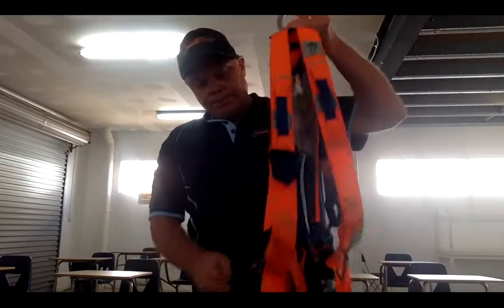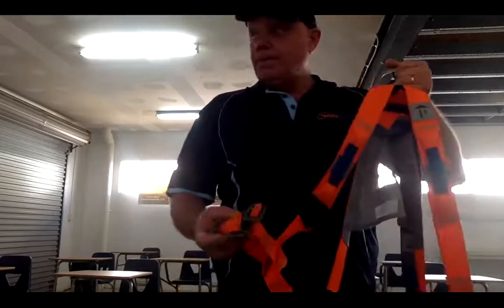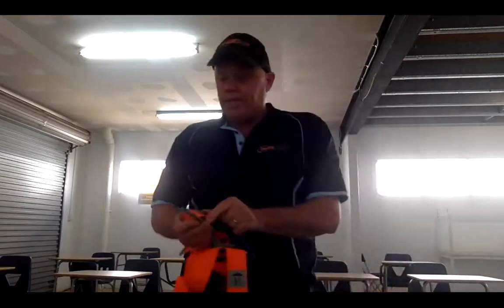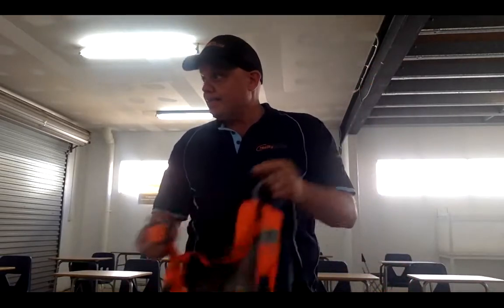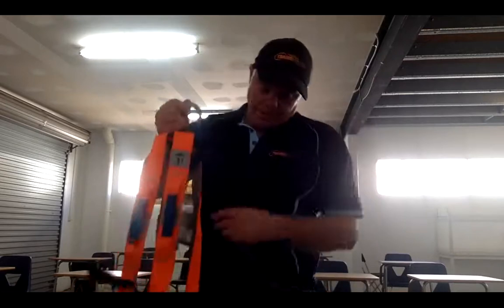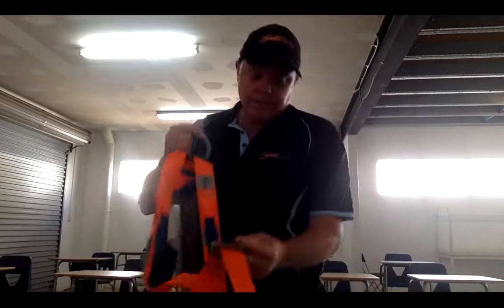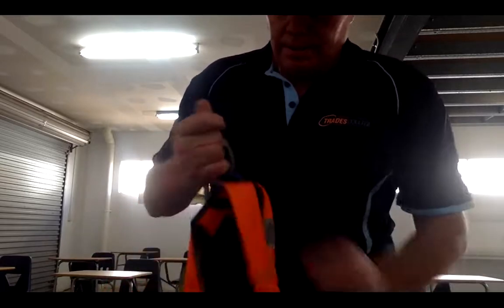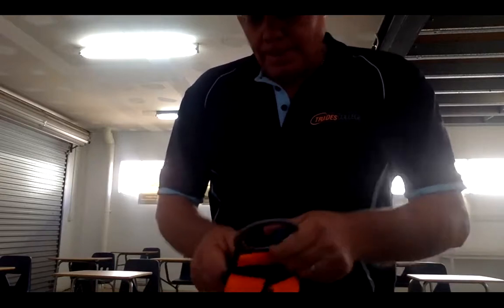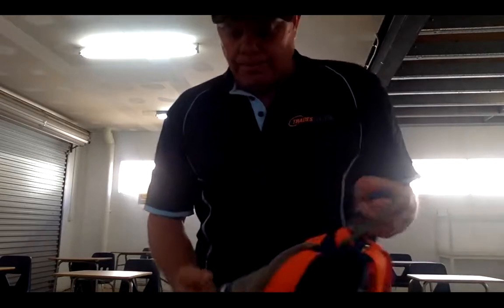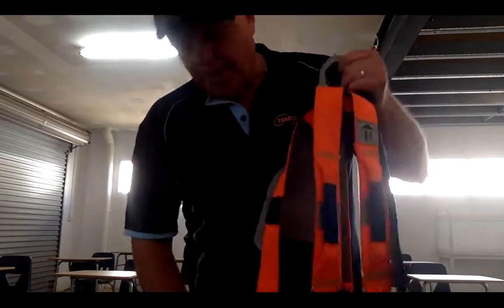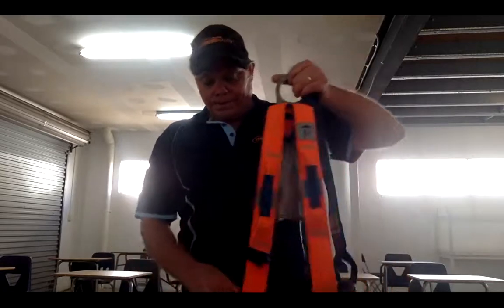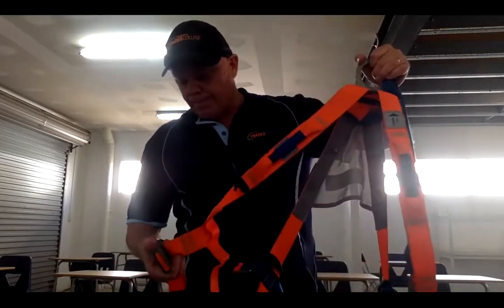And also the buckles, okay? So with the buckles, we've got to look at whether there's any warping or pitting. So go right over these buckles here, okay? Just a thorough inspection. And just remember the whole time you're doing this, if you're going to wear this harness, you've got to make sure it complies with all these safety standards. Otherwise, you can rip and tear.